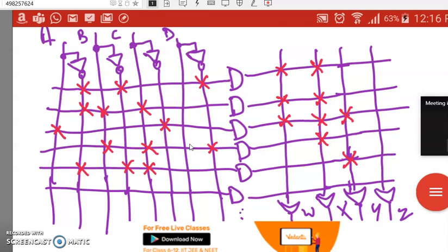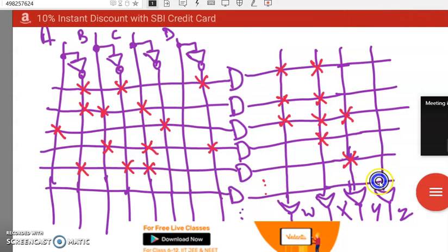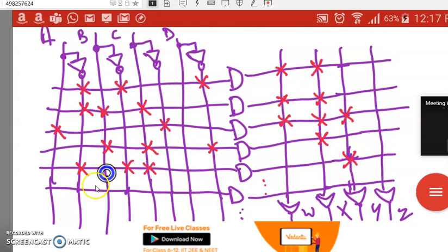Like this, you should go through your program table, or what you have written there. Every row, wherever you put 1, only those connections you put on the output side. If you have written 1, connect that variable directly. If you have written 0, connect to the inverter output of that variable. Like that, you go row by row in the program table and make the circuit connections. It's not completed yet. You have many things in between. You should connect all those and then connect appropriately for these outputs as well. Only then will the circuit be completed. Here it is an incomplete circuit only.